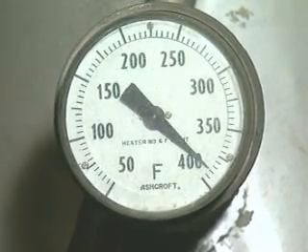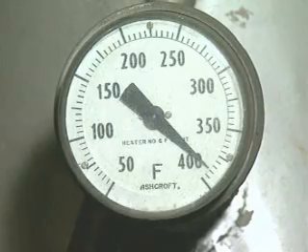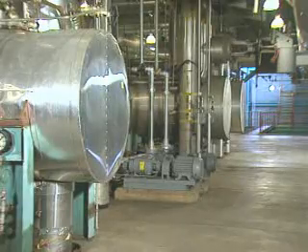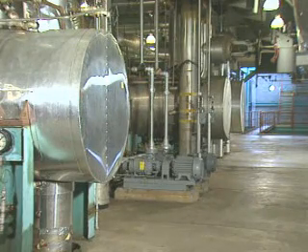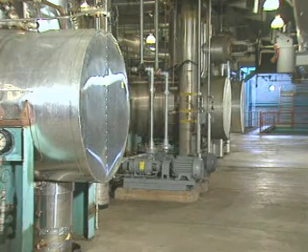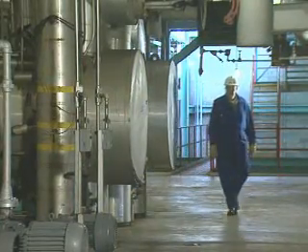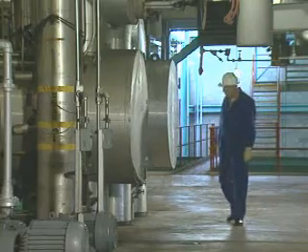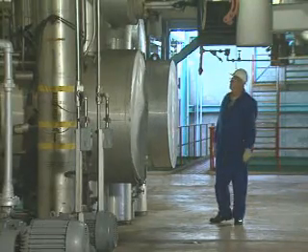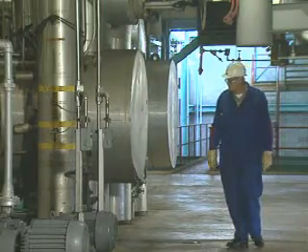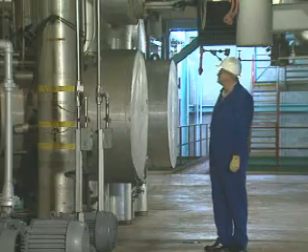Checking this temperature is the quickest way to get an overall picture of how well the feedwater heaters are doing their job. If the final feedwater outlet temperature is at the expected level for the given load, then each of the feedwater heaters in the train is probably transferring heat at the proper rate. But sometimes a heater within the train may be transferring heat at an improper rate, even though the final feedwater outlet temperature is at the expected level. So periodically, you should also check the outlet temperature of each heater in the train.